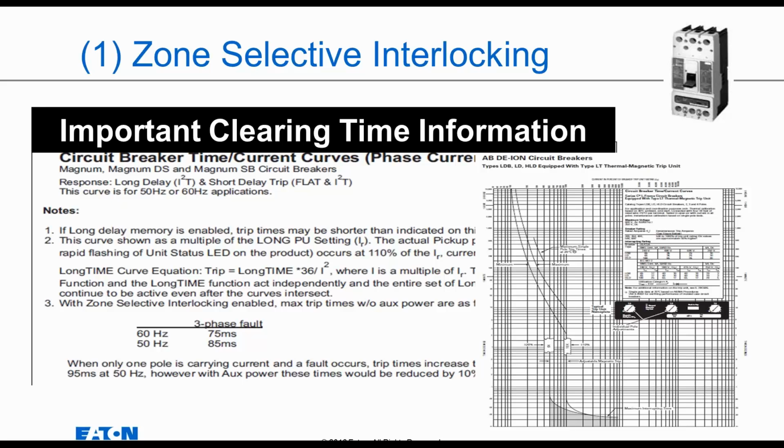You have to be very specific, and on one of our breakers, we actually tell you the time delay for 60 hertz versus 50 hertz. So these curves, which used to be looked at with just the naked eye, are now looked at under microscopes. People are trying to get as close protection as possible with each curve and maximize their system. There's nothing wrong with it. It is just better design now.